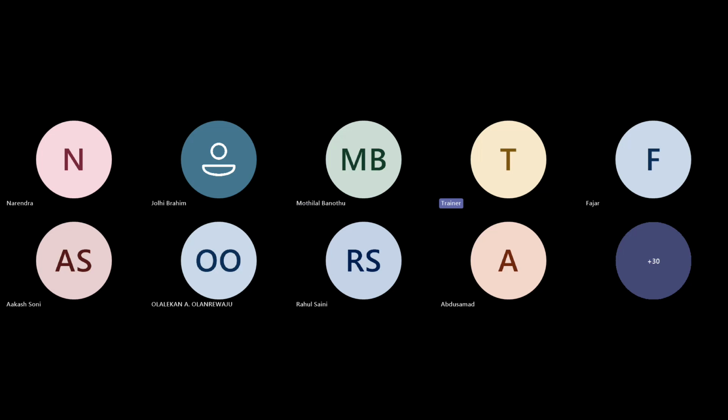You have to select while sizing the vessel. You have to define how much particle diameter you want to separate, like 5 microns particle diameter in the separator, or up to 1,000 microns. You have to define. And if you wish to see how much it can separate, you can use the GPSA equation. You have to put in the dimensions and physical properties. It will give you up to what diameter the selected vessel can separate.